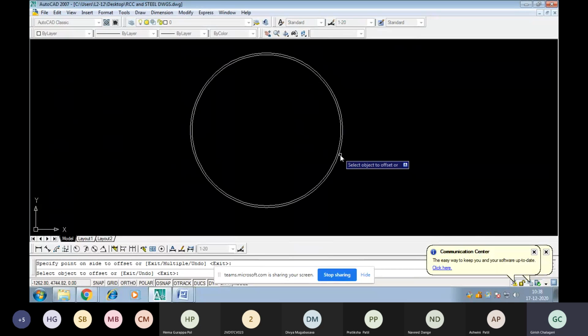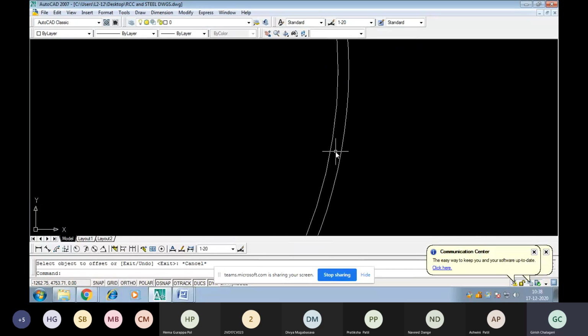See here, in this I should provide the reinforcement. Again, I can provide it like this. So offset, providing 30 as cover divided by 100. I have given 30 cover, so reinforcement will be provided like this. Otherwise, offset 160 is 80 divided by 100.